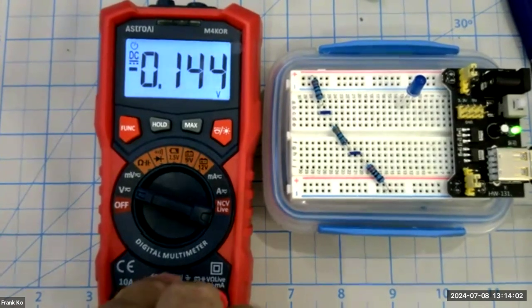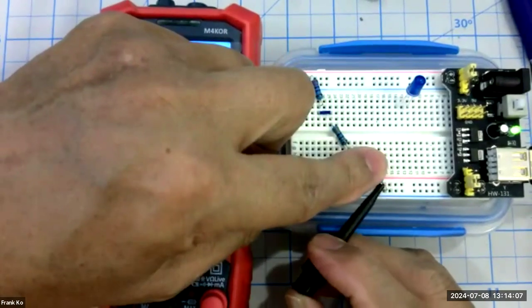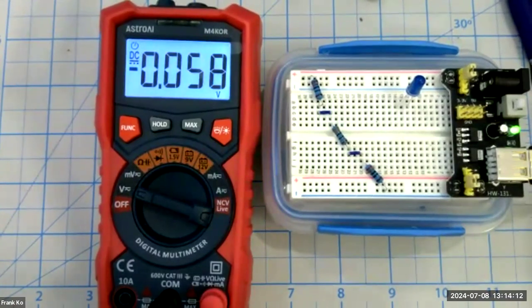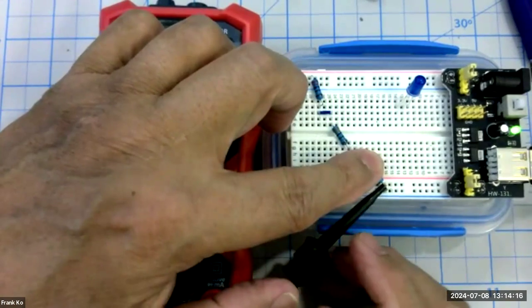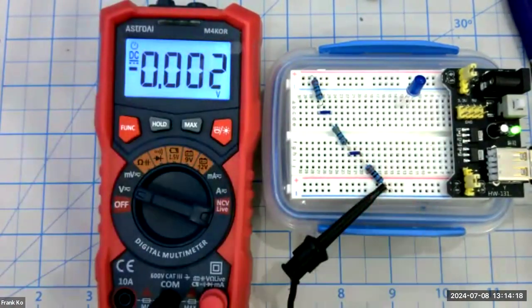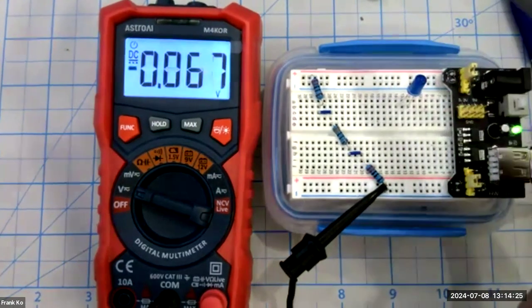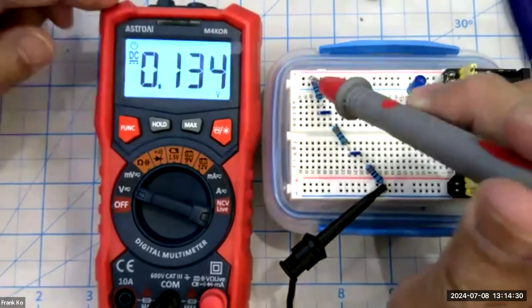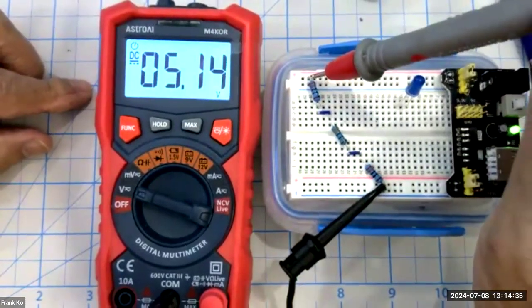So I'm going to change the lead for just a moment. And this will be the one-hand technique. So I'm going to use a hook. Oops, come back here. And use the hook. All right, there. So now the black is hooked to ground. All I have to do with one hand, as I've said, is touch test point number one, which is voltmeter number one, at the top of the circuit. So I go to touch, bend the resistor here, touch right here. I expect 5, I get 5.